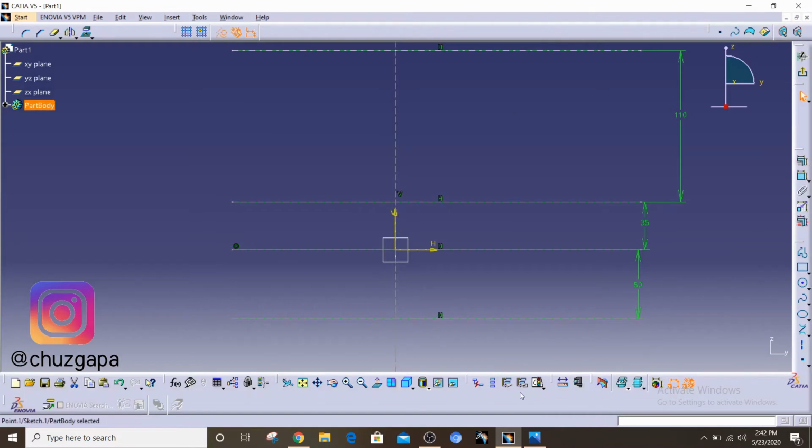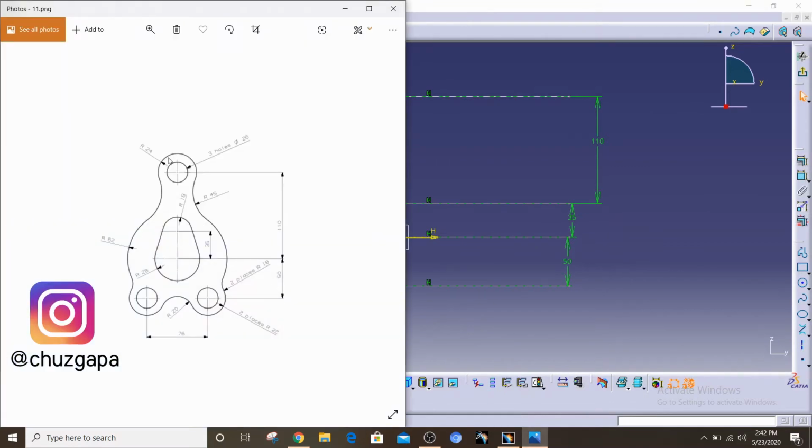After that, I'm gonna start from here, from the top. So I'm gonna make this circle. I can make arcs, but I'll just use circle commands to go full figure. One more thing that you notice here is that we have a lot of curves. I think this whole thing is made from curves. So we have one curve, one arc, 2, 3, this small arc, 4, 5, and 6. We got 6 arcs, and we're gonna just use circles and tangential commands to join them together, and then we're gonna trim off the rest of the circles here.